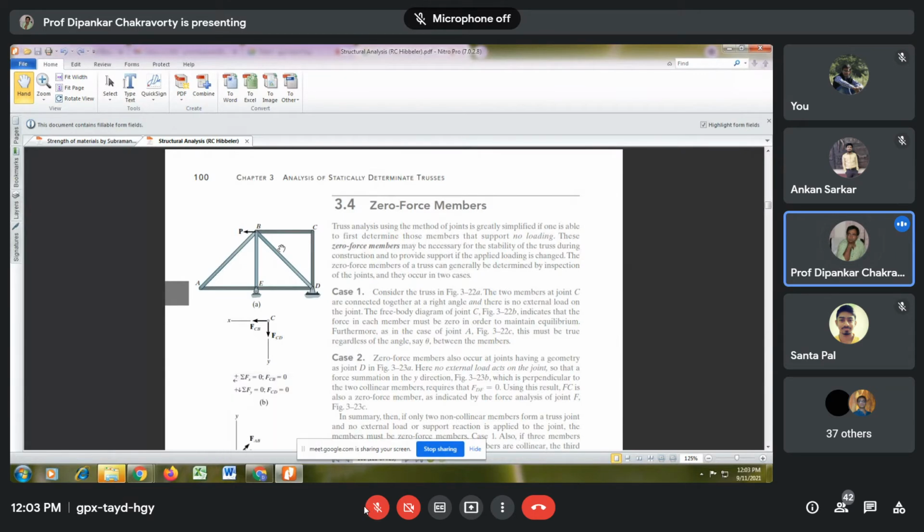Okay. Now you come to joint C. What is your observation about bar force BC and bar force CD? Both are zero force members. Okay. You come to joint E. Member AE is a zero force member, so it is not there.